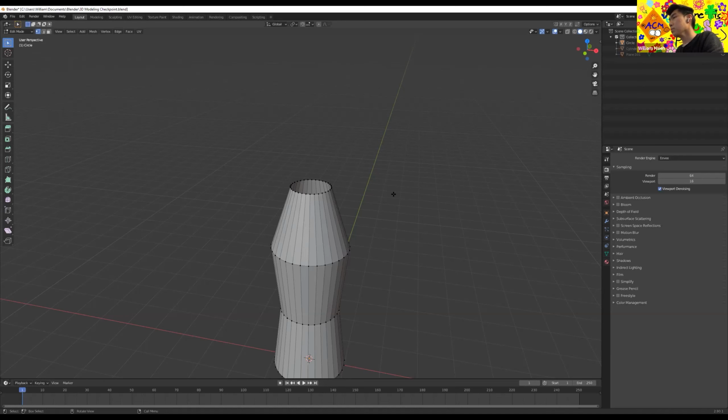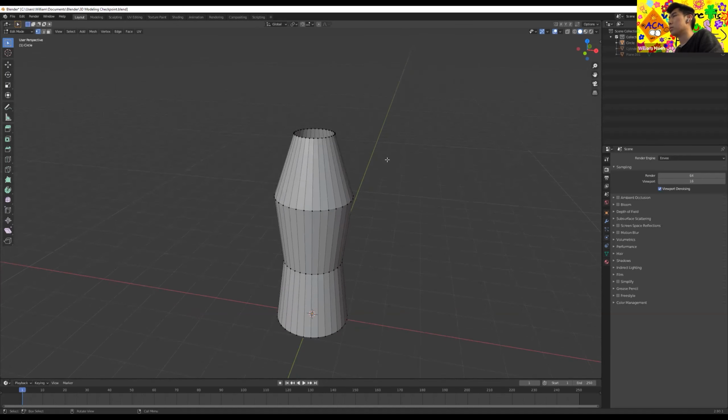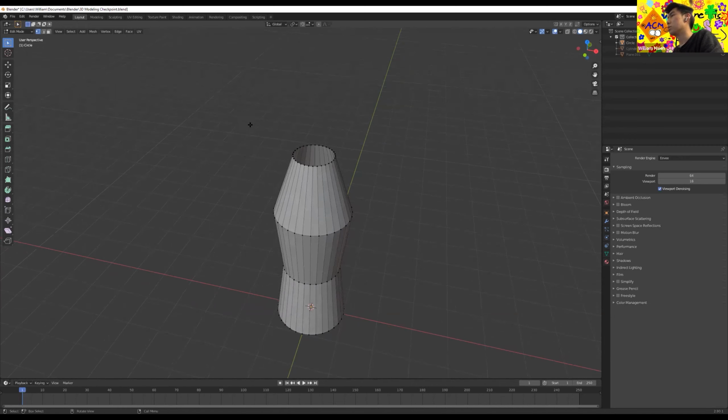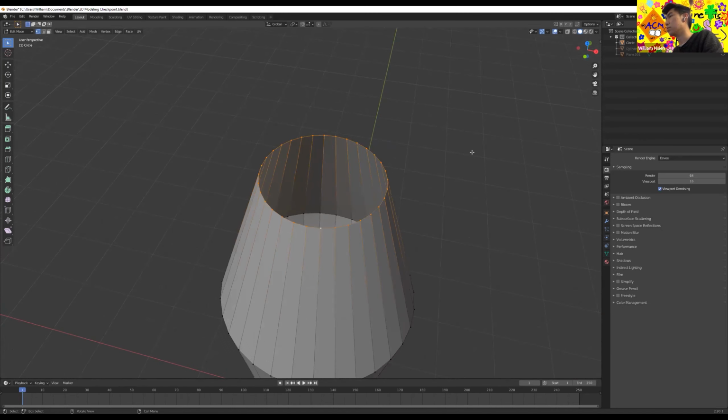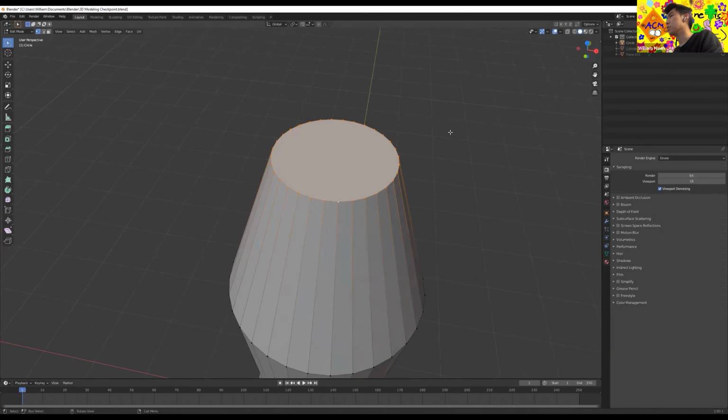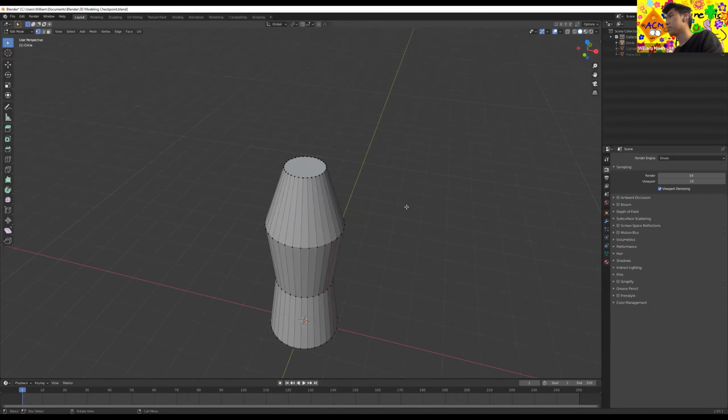All right, now that everyone has had time to do this, this is a small thing, but select the top ring. You can alt click and we're going to press F and that fills the face so that there's not a hole inside. Before, you could see through it, after you press F, it fills it and you can't see through it. Press F, yes. Like the same key you would press to pay respects, if that makes sense.